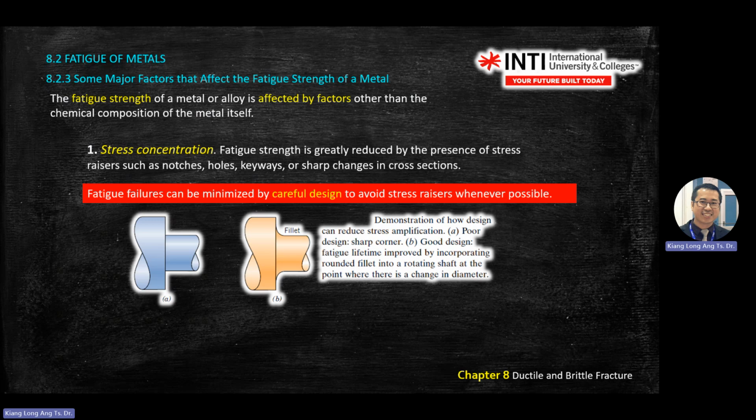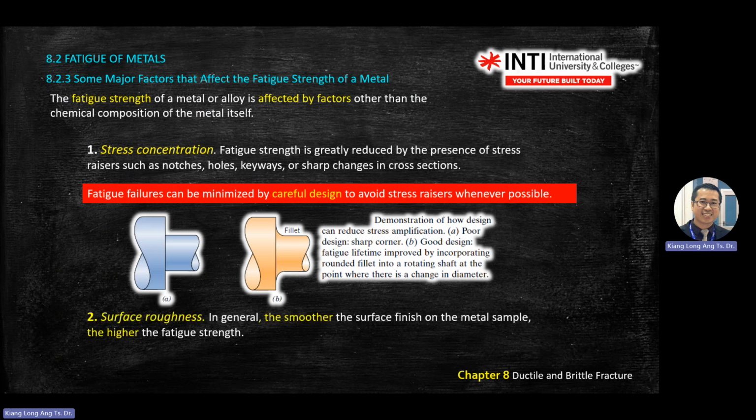First, stress concentration. This one you need to discuss a little bit for the machine one. So this one is with fillet and without fillet. This is how you improve the design: reduce the stress concentration by having a fillet.